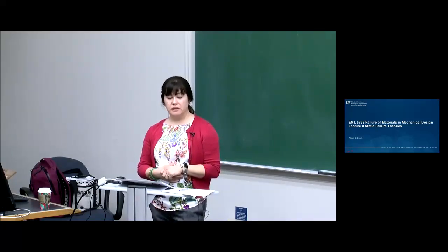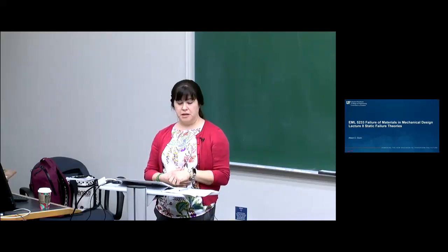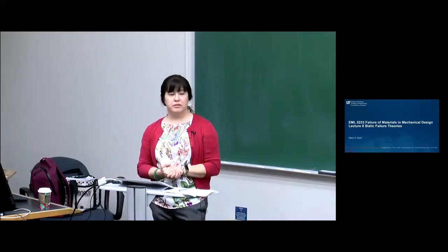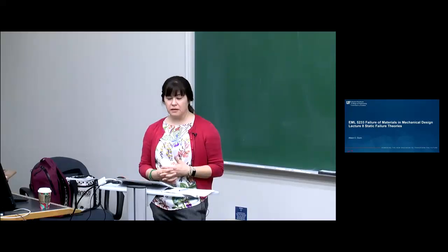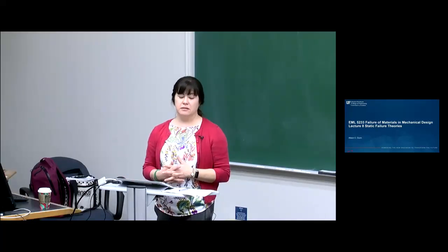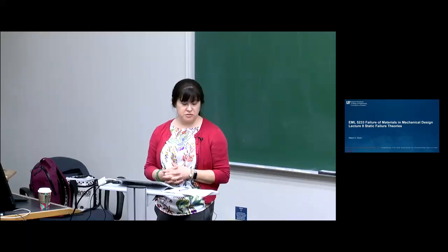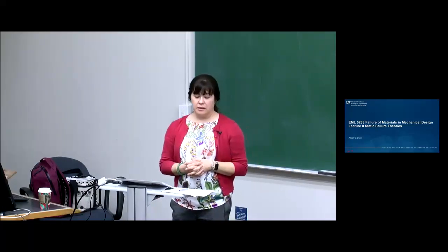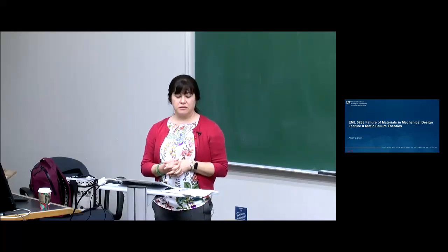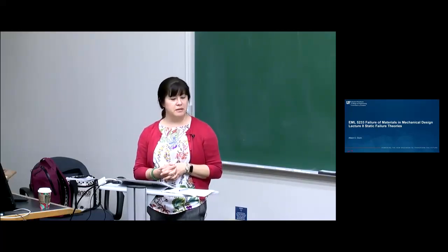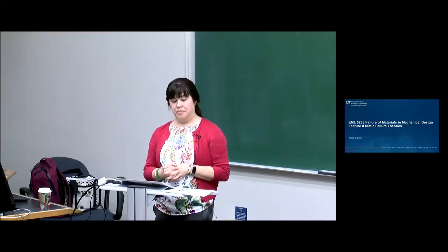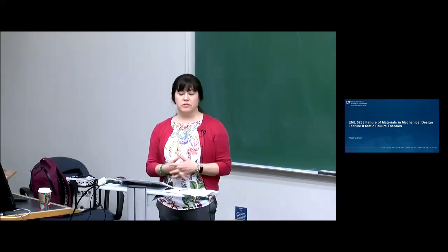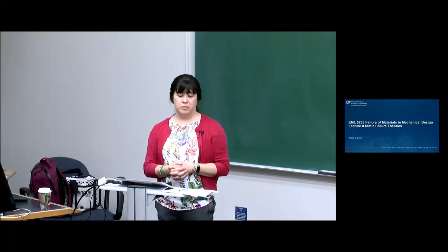And once we start talking about cyclic loading, it'll open up sort of a can of worms in terms of other things that we have to consider. So one of those is stress concentrations. Just want to give you like sort of a preview. In static loading, stress concentrations are not as important because of strain hardening. But when we have cyclic loading, fatigue loading, stress concentrations do become much more important.